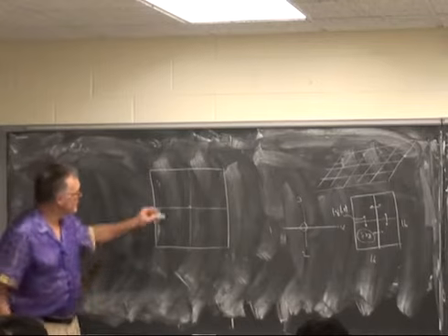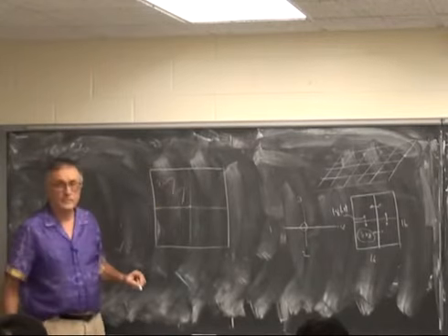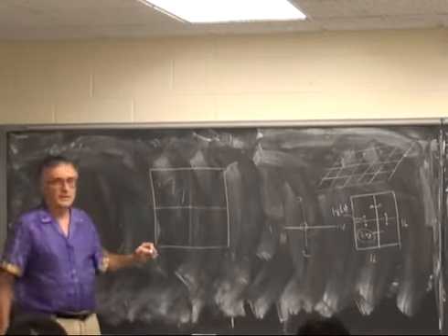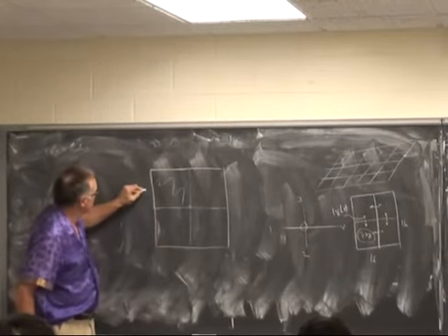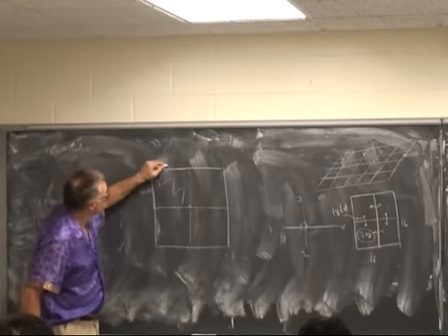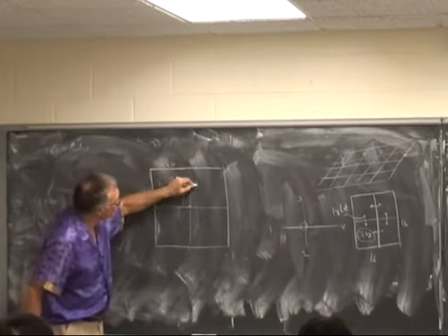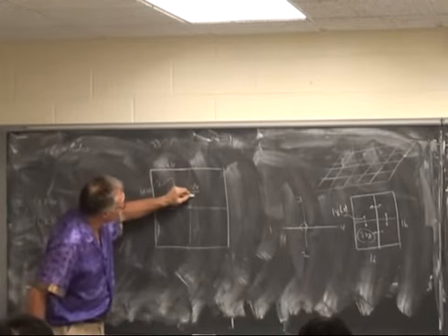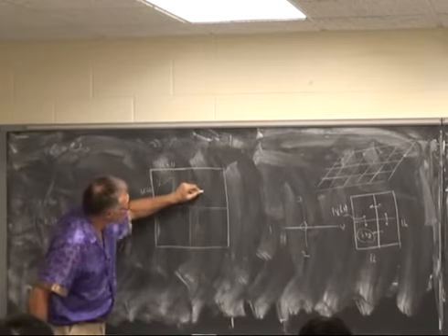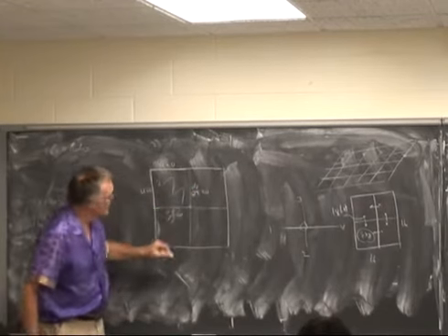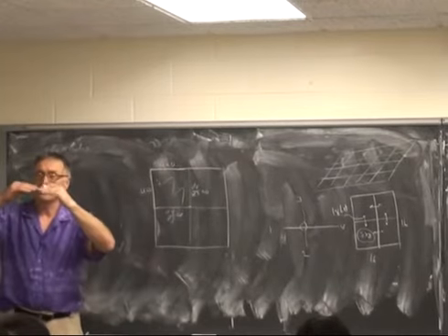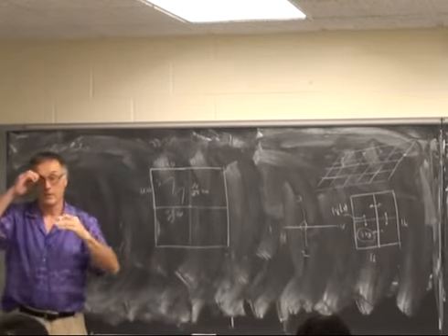For the boundary conditions, you only compute this quarter, but this side is held still, u equals 0, and these two sides have du dx equals 0, and this side has du dy equals 0, because you have to have continuity across the break.